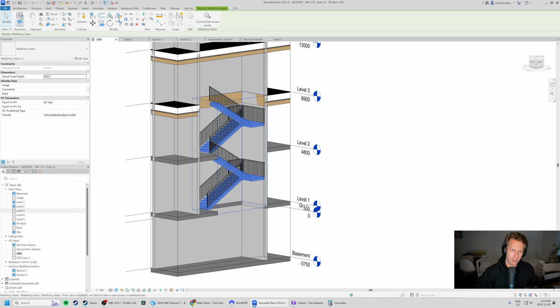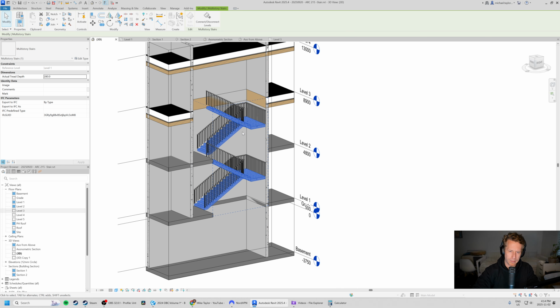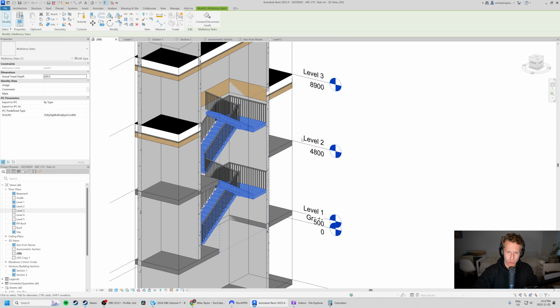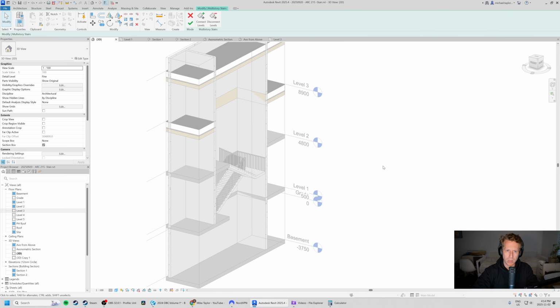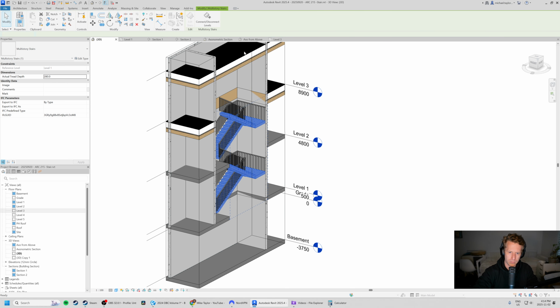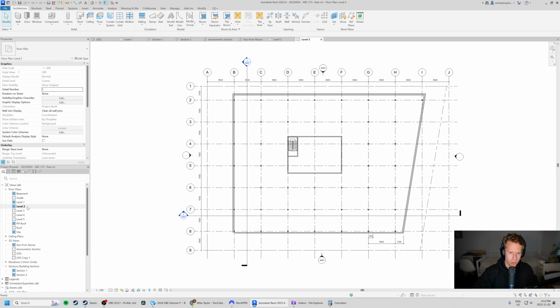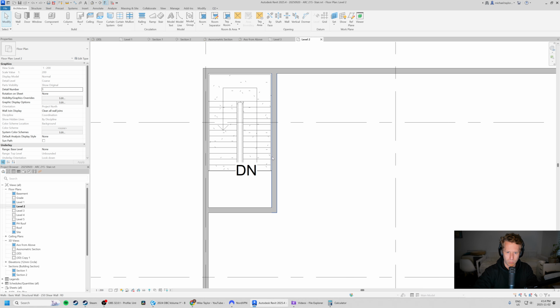So oftentimes inside of Revit, you're like, oh, I've found this really amazing tool, and this doesn't look quite like what we want. So we're actually going to have to come back in and draw at level 2 to level 3. So don't do it that way. We could do it for the following 3 floors, but that first floor being different changes the way that the stair works. So let's just go back and undo that. Let's go to level 2. Where's my level 2? And we're going to see the stairs below, so don't let that distract you. For now, I'm just going to hide this whole zone. Otherwise, it's going to confuse everybody.